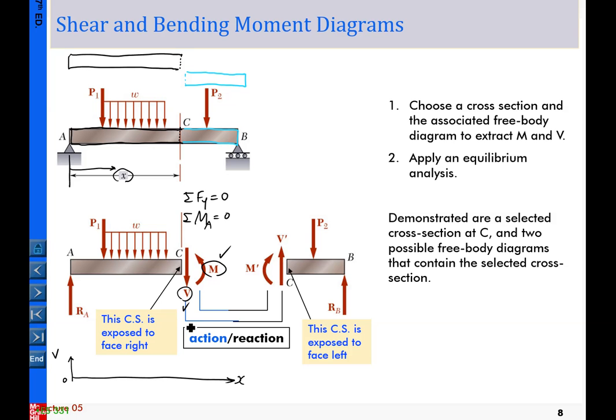So now, for example, here you have calculated V. Say V is this value, you calculate it. For example, say V equal to V0, you calculate the V0 here. Then right now you simply keep changing the selection of the cross section. You simply sweep your selections throughout the whole cross section. Basically, you should be able to build up the distribution of the V, and then you simply connect the points, and then you come up with the curve. This is called the V versus X, the shear diagram.